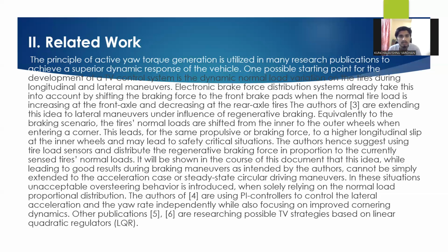The authors are extending this idea to lateral maneuvers under the influence of regenerative braking. Equivalent to the braking scenario, the tires' normal loads are shifted from the inner to the outer wheels when entering a corner. This leads, for the same propulsive or braking force, to a higher longitudinal slip at the inner wheels and may lead to safety-critical situations.